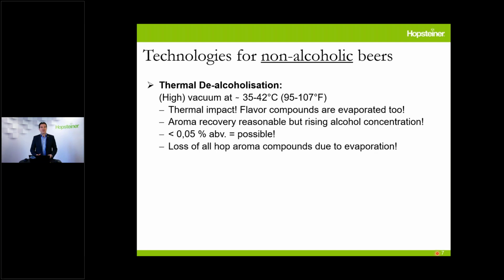And the dealcoholization is a physical game in between temperature, time, and vacuum. The higher the vacuum, the lower the temperature can be to come to the same result of low alcohol concentration in the beer. Problem is that all the flavors are evaporated too. And if you ever have a chance to taste a dealcoholized beer behind the machine, you will be very disappointed, because there's nothing remaining other than a little bit of water, a little bit of maltiness, and a little bit of bitterness from the hops. That's all.